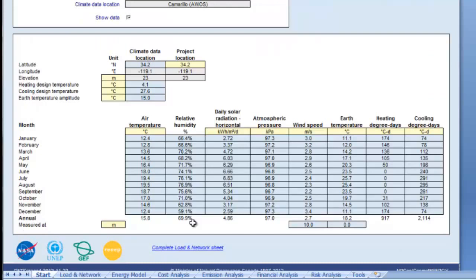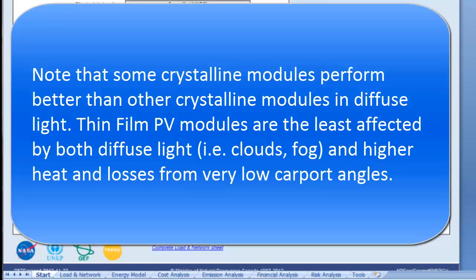Another key difference between coastal and inland sites is that coastal areas typically receive a great deal of morning fog, which reduces solar radiation levels. As a result, inland sites might receive an additional 9% more radiation than those in coastal areas. Hence, we can expect around an overall 10% increase in the number of kilowatt hours produced by an inland system compared to a system on the coast.